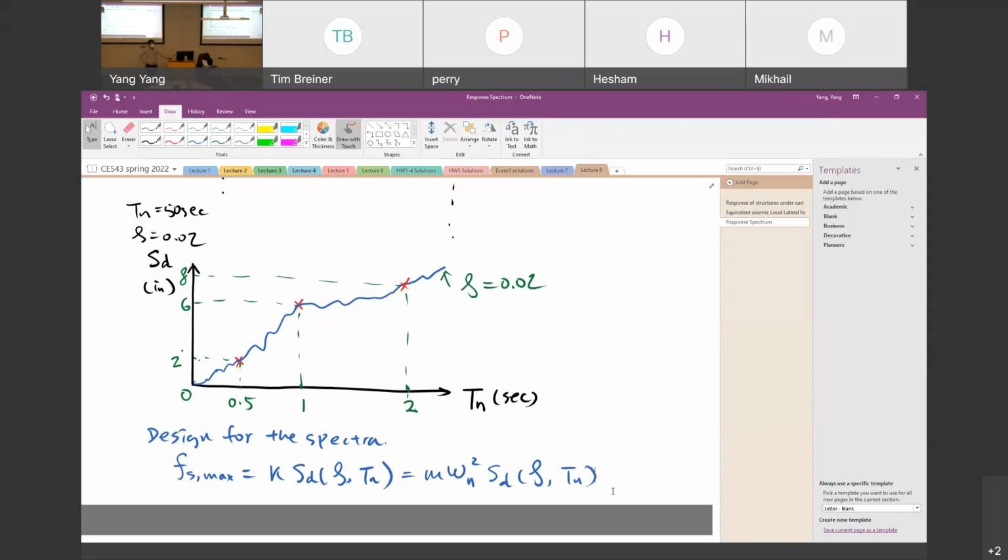Does that answer your question? The damping is very complex. If somebody can develop a method to calculate the damping ratio of the structure based on some theoretical numbers, I would say that person will get a Nobel Prize for physics, I believe. Damping ratio is very difficult to calculate theoretically. It's a research project.